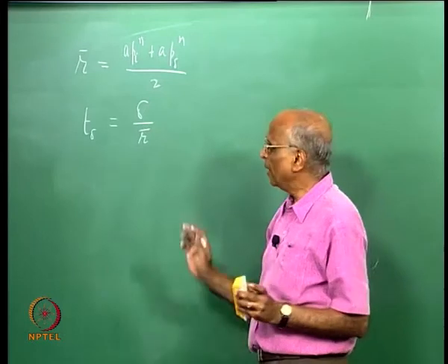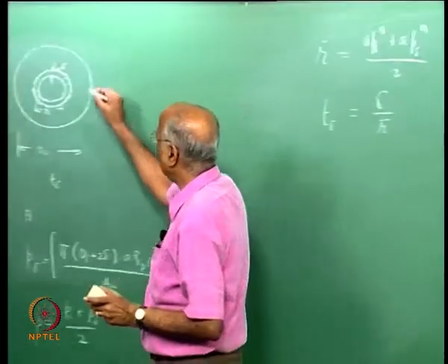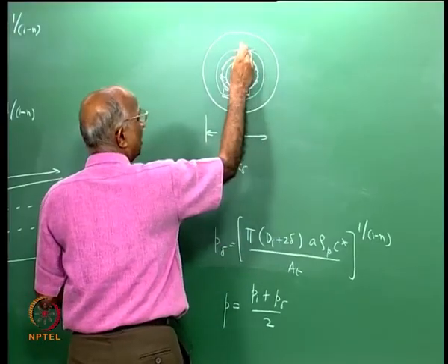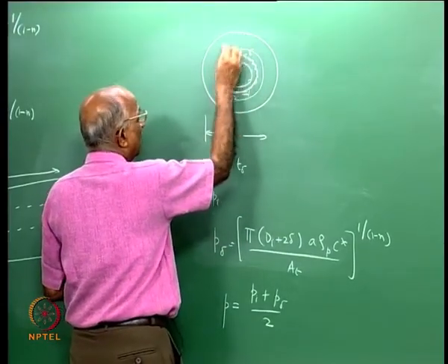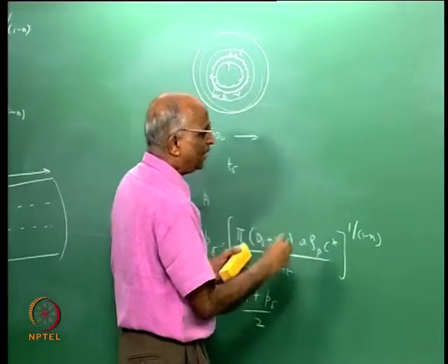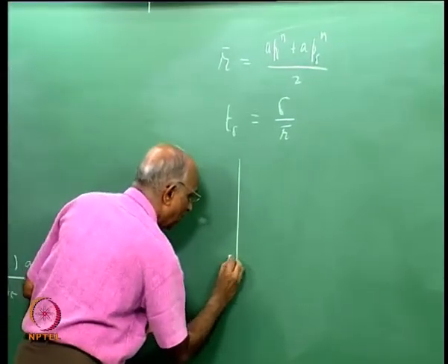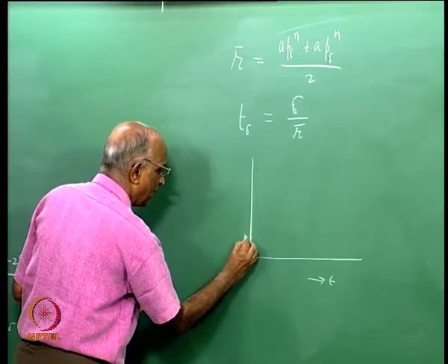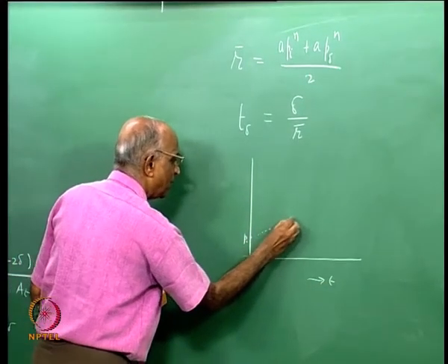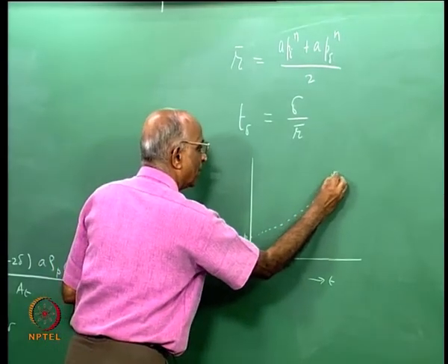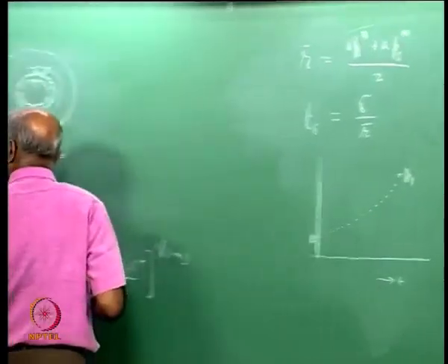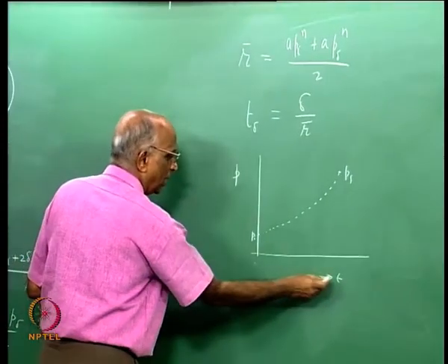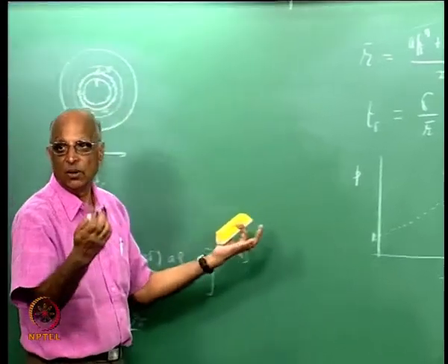Okay. Now, I do the same thing. I now take this as the initial condition. I go to the next step. I find the value of T consumed. I get the value of T consumed, and then I can put the whole thing together and say, as a function of time, my pressure increases from Pi. I know all the intermediate values. I know the final pressure is Pf, which is given over here, and this is how the pressure evolves in an inner burning rocket.